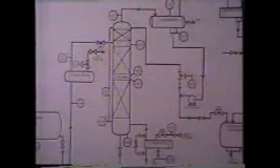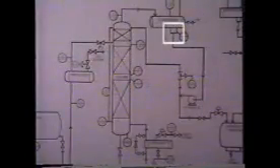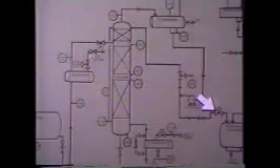Now that the flow of feed has been stopped, the level of overhead product in the condenser leg will drop. When this happens, the condenser leg level controller will automatically close the overhead product takeoff valve. The outside operator then shuts off the reflux pump. Finally, the outside operator breaks the vacuum and shuts off the steam jets. He does this because in an emergency, the system may lose steam. Shutting off the vacuum system prevents water from being drawn back into the column from the steam jet condensers.